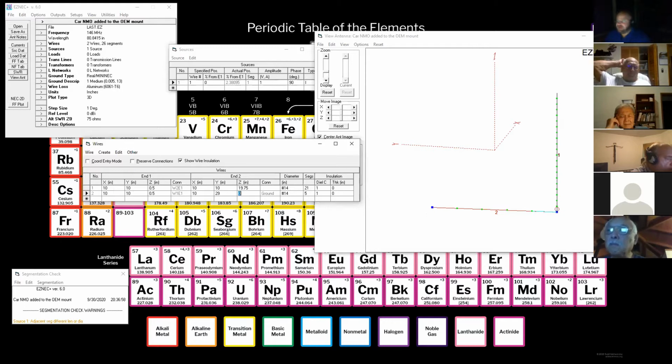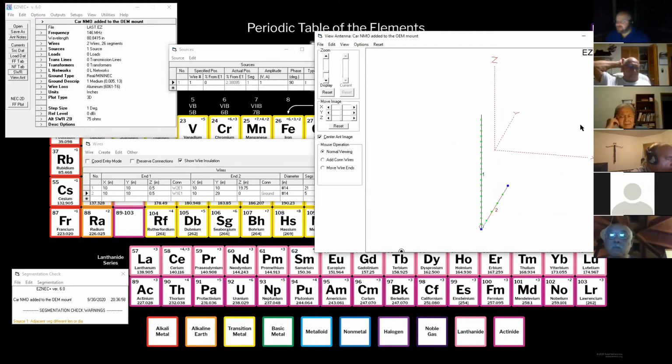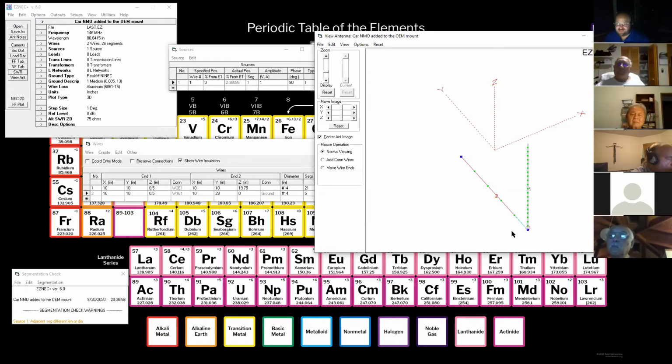the side. Now that I've got 2 wires, you can see that I'm offset from the 0 point in this model. And I do this a lot because I don't want my poor old eyes to see these lines and think they're antenna elements. So you don't have to offset your models from 0. You can leave your X and Y at 0 for your starting point. I just don't, because I have before, sitting here at night, mistaken these for antenna lines. So I've got this one radial here.